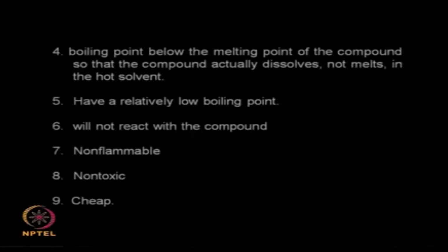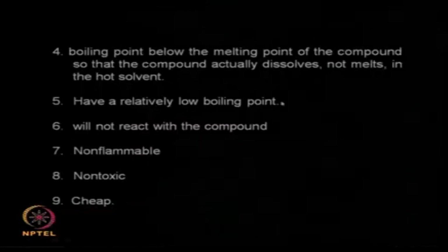and the boiling point of the solvent should be much below the melting point of your compound. Otherwise what happens, if the boiling point is very high, then your crystal will start melting. If it starts melting, then it will be very difficult for you to separate out, and if the solids melt it will form tarry product, it will not be accepted by the customer. So it should also have a low boiling point.